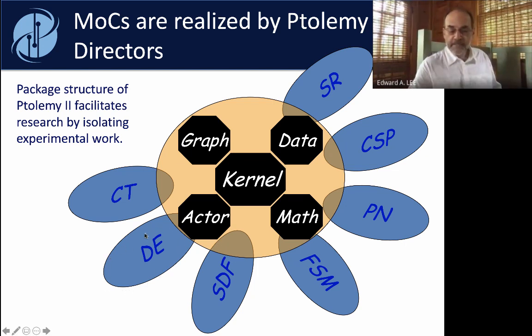And so it's a type system that, first of all, is very polymorphic. So a lot of the components are very flexible about what data type their input ports accept and their output ports produce. And when you connect them with other components, the data types will be inferred. So any component that constrains the data type imposes those constraints on the rest of the model. And so the inferred data types propagate throughout the model from those constraints.